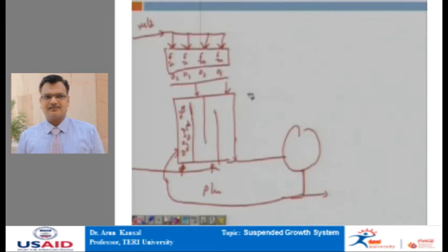So, we are not wasting oxygen supply anywhere because it is evenly distributed and it is therefore efficiently utilized. Multiple point introduction of wastewater maintains an activated sludge with high absorptive properties. As you know, the absorptive property of a flock reduces as it is exposed to more food. If I draw a crude analogy, if food is available to one person, initially he will consume more if he is hungry, later on less.